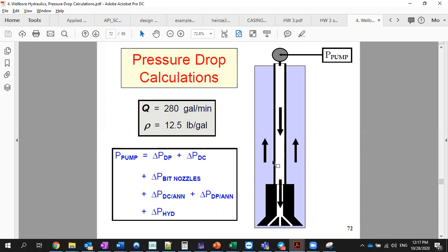Another thing, you also have the pressure at any point. That's the general pressure at any point. If you have a static system, that pressure is equal to the hydrostatic pressure. If you have a flowing system, then that pressure loss will be added to the hydrostatic pressure. That gives you the pressure at that point. So just to make it more clear, hopefully. If you guys have questions as I talk, don't hesitate to ask.